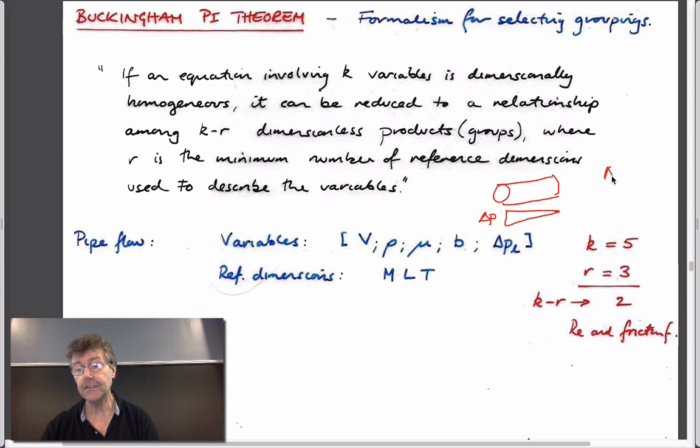In this particular example, taken from the book, the change in pressure with length is dP over dx along the pipe, the pressure gradient, so that's this term here. I didn't notice this, but maybe this is for the duct, doesn't really matter. This is the diameter, this is the average velocity, v, and density and viscosity are the same as we had.